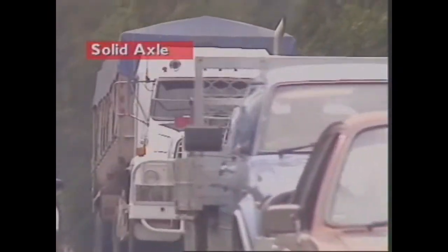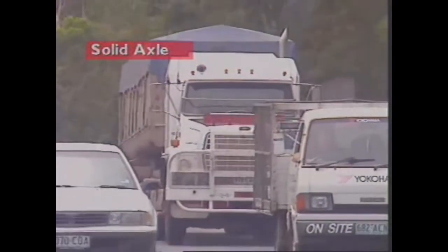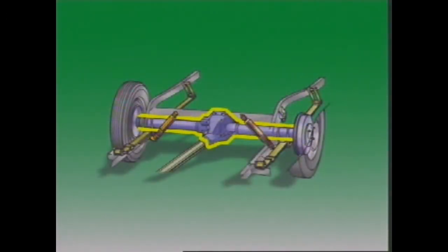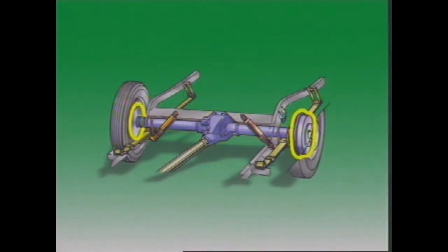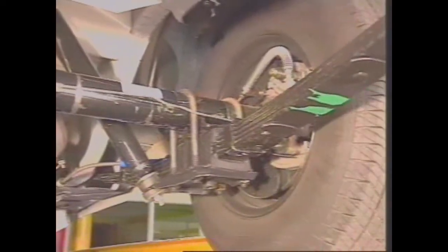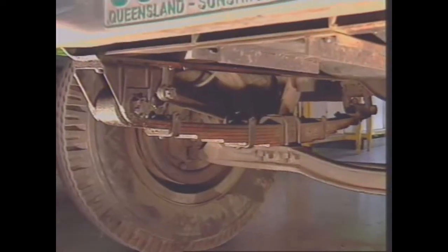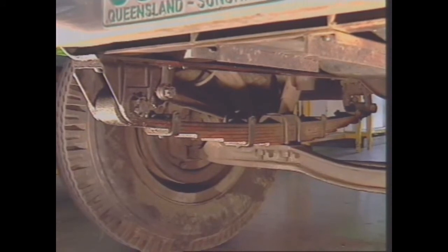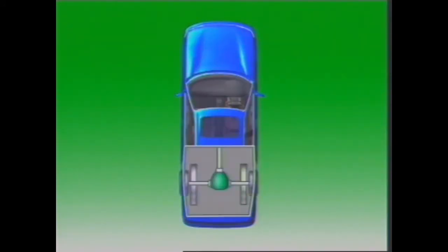This section examines the solid axle or beam axle. The solid or beam axle provides a simple means of locating and mounting the hub and wheel units. Together with leaf springs, it forms an effective non-independent suspension system. Similarly with coil springs. It is still used in the rear suspension of many front-engine rear-wheel drive cars and light commercial vehicles, and as the front suspension on many heavy commercial vehicles. On rear-wheel drive vehicles with leaf springs, the axle housing is held in place by the springs and no other form of location is needed.